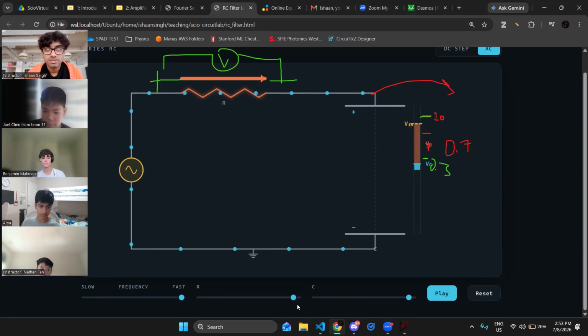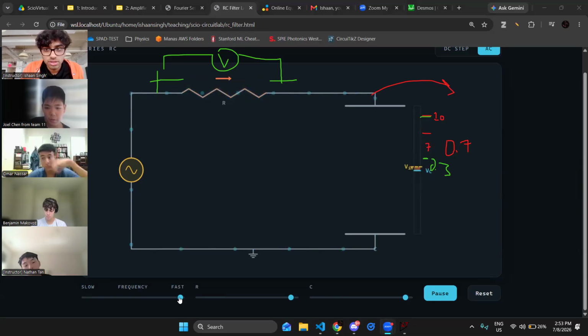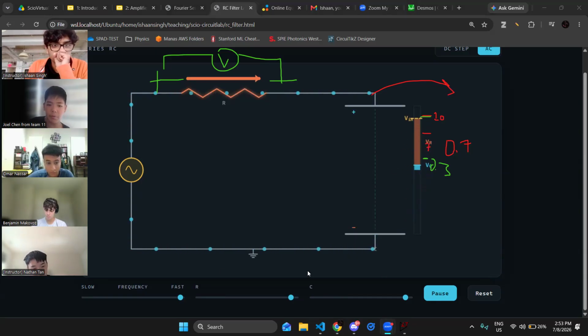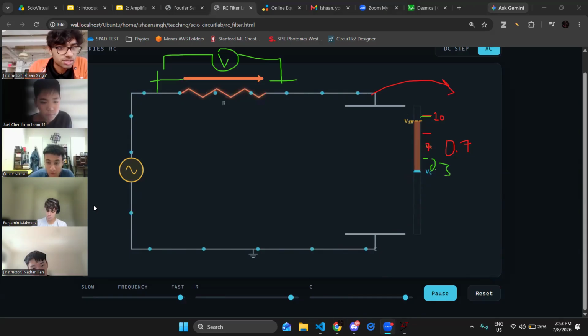So what about the reaction speed? Is the capacitor going to be slower to react or faster? It's going to be slower to react, because it needs more time to charge and build up voltage to the full charge. Exactly. So even at this slow frequency, the capacitor can't keep up. It's just so slow because of its time constant. Okay, so that's it for the demo there.